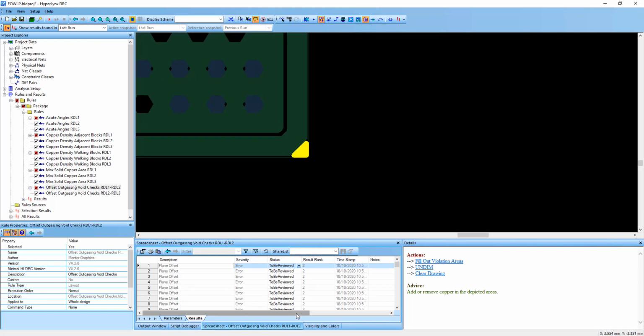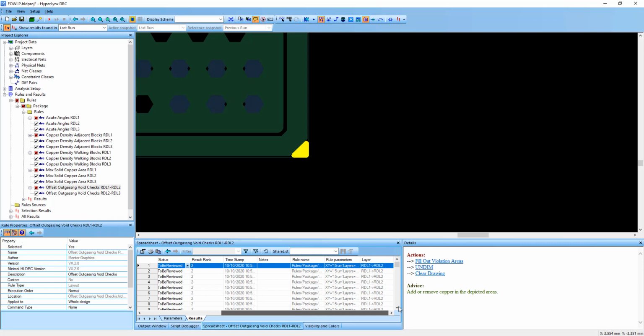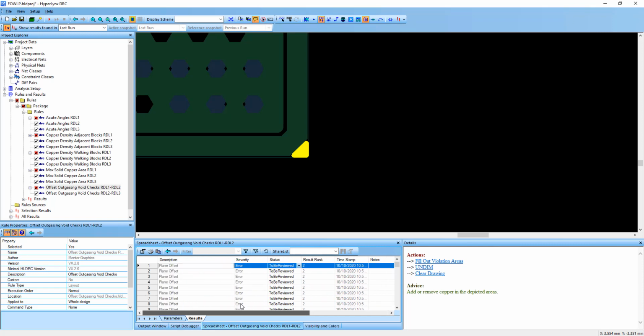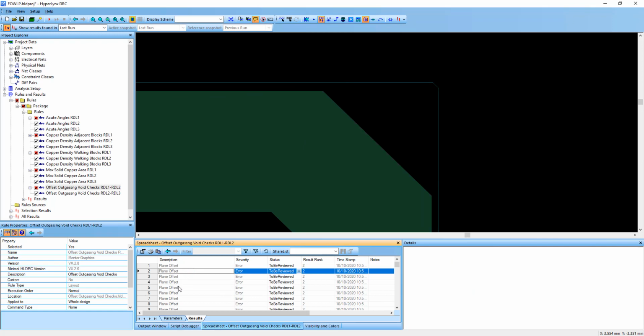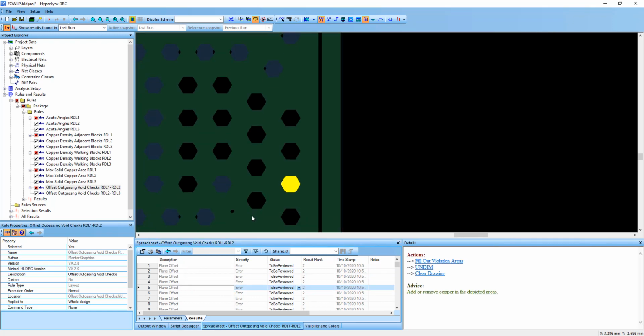This rule checks the design to see if any 2 layers have a hole bigger than the specified XY distance that you can see through 2 layers. The lit up areas of these violations show where the crosshatch doesn't line up. Hyperlinks DRC now contains these 5 IC packaging rules out of the box, left shifting some of the final sign-off